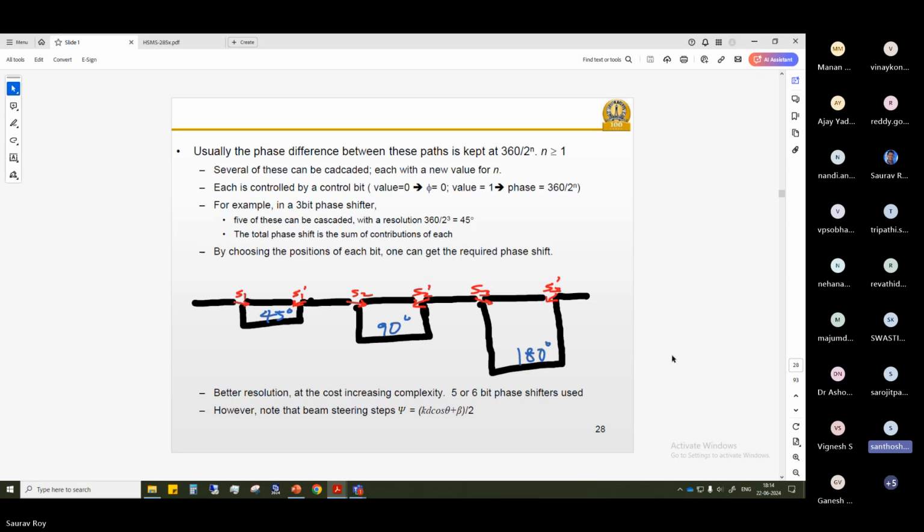If we give input to the two RFs, then the intermediate frequency will get I and Q. LO is our normal port only, it is given to the 90 degrees coupler, and then I and Q come out. Here, it has nothing to do with I and Q. It is only a simple RF signal you are giving.